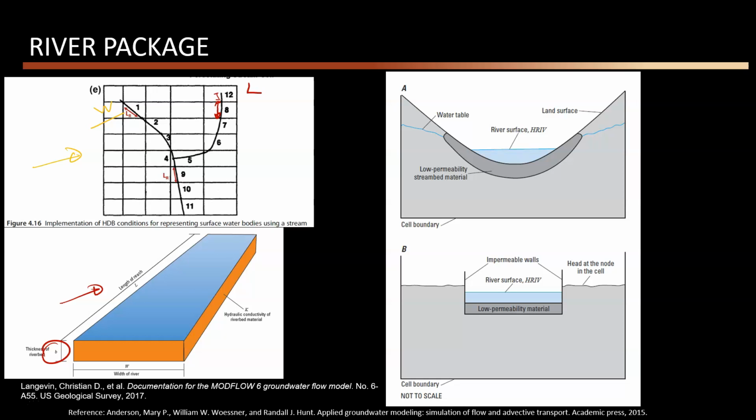It also asks for the thickness of the aquifer, so you input this information. That would be different for each cell, or constant for the entire system. This is extra information that we need to provide. The width of the stream, the W term, is also something that we need to give. So having L, thickness, and W, I can calculate the Q, right? This was the C, a similar formula, where C itself is a function of K, thickness, and area.